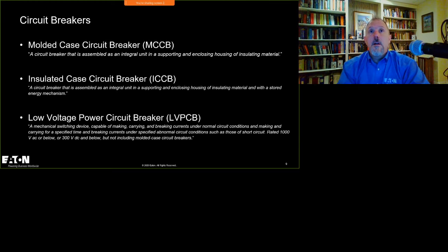Now, we sell dry type transformers with built-in circuit breakers, but the key thing there is, remember we had the 75 C discussion. Heat is not your friend, my friend. Heat is not your friend. So when you put an overcurrent device in there, and you don't have enough heat dissipation, you could create an issue. Our transformers are listed, and we've tested them with the circuit breakers built in. That assembly was listed and tested, and we understand the heat rise, and we know we can pass those heat rise tests and things of that nature.